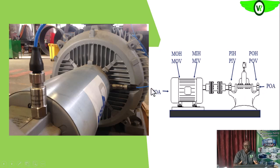So in a single equipment, a complete pump train like this, we will take at least 10 vibration information. That is at least 2 from each bearing, and we have 2 bearings on the motor, 2 bearings on the pump. So we'll take between 8 and 10 vibration information.